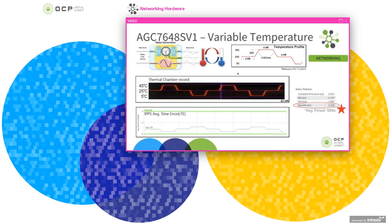It indicates that our system is very stable even under thermal shock, because the timing depends hugely on the stability of the oscillator. Here we use an OCXO, oven controlled oscillator, in order to stabilize the timing system against thermal shock, so we can gain a very nice result here.